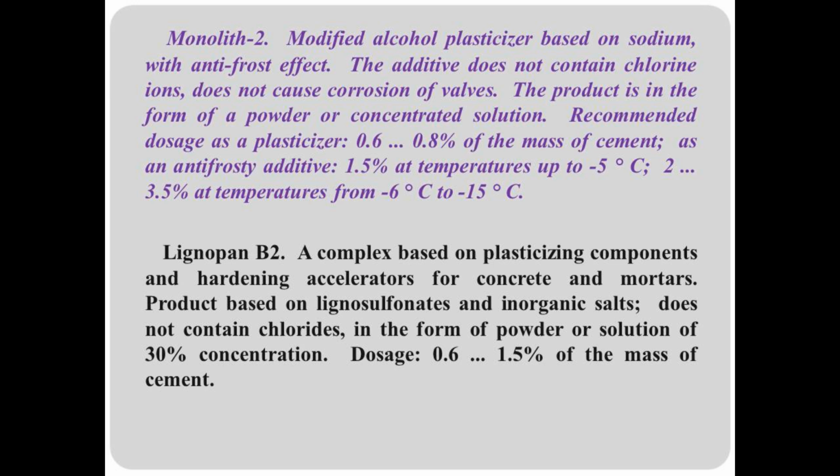Product based on lignosulfonates and inorganic salts, does not contain chlorides, in the form of powder or solution of 30% concentration. Dosage 0.6 to 1.5% of the mass of cement.